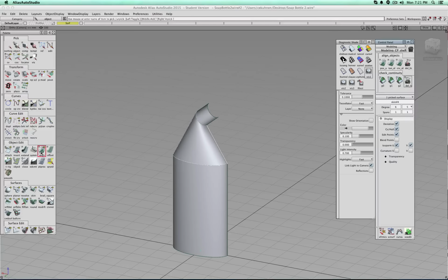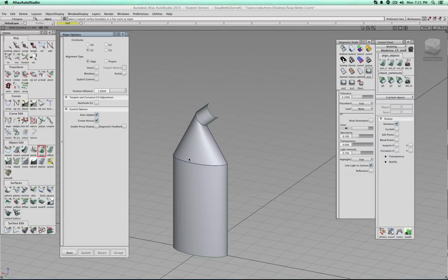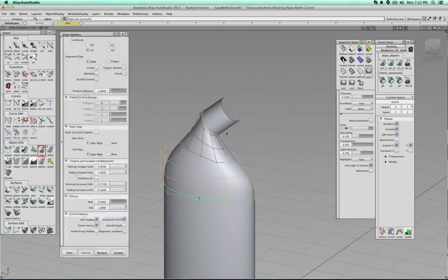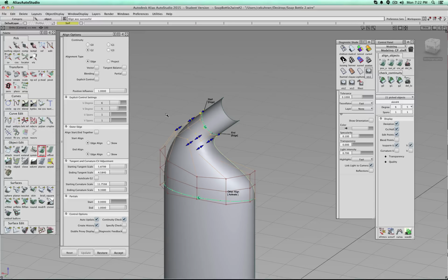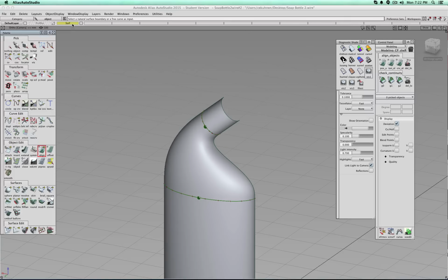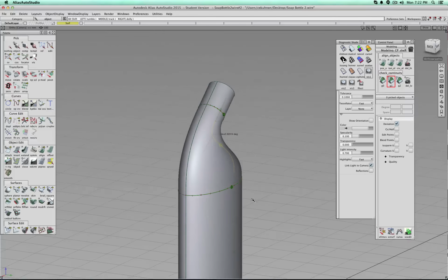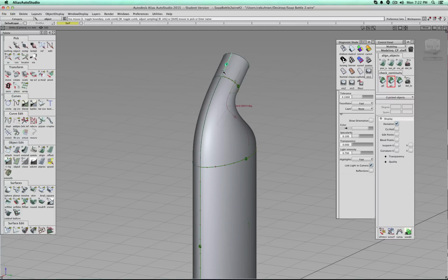So now I can go to align, sorry for the hiccup, hue to hue, G2, that's all good. Check continuity, you see a C, perfect. And then here to there, that's also clean, good. Then let's cross fingers, turn on symmetry, because now we have to check those edges. We know those are tangent and this one is not tangent. So is this one.